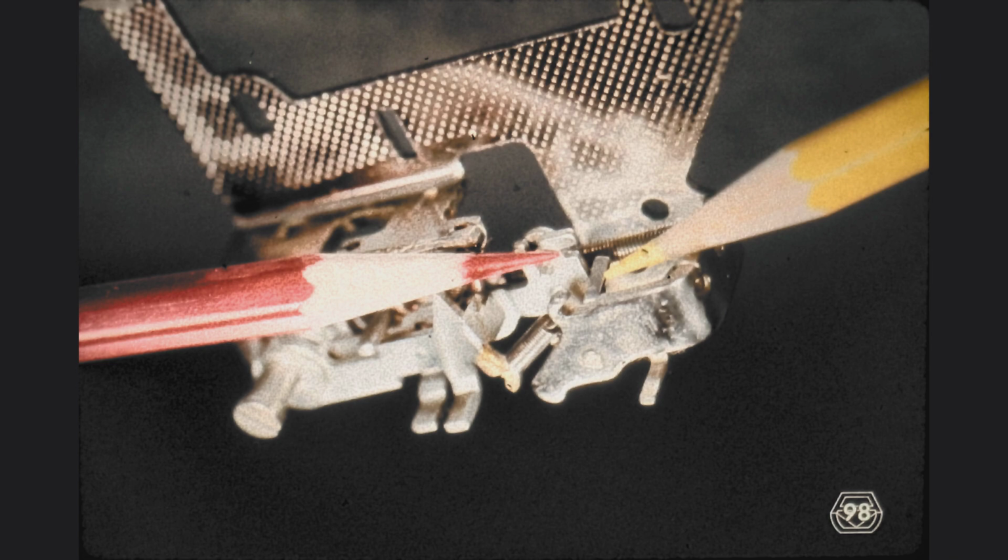If you have an old-style tabulation lever, be sure to check the position of the tabulation lever overthrow plate, as was explained in Program 10.2. With this, we have concluded all of the adjustments which have to be made as a consequence of repositioning the keylever up-stop, or guide. After you have checked the tab torque bar link adjustment on your machine, we shall turn our attention to the 2 remaining keys located outside of the keyboard frame.